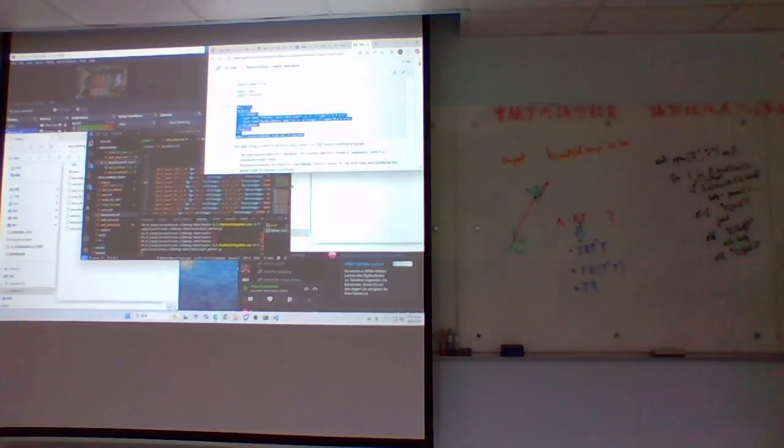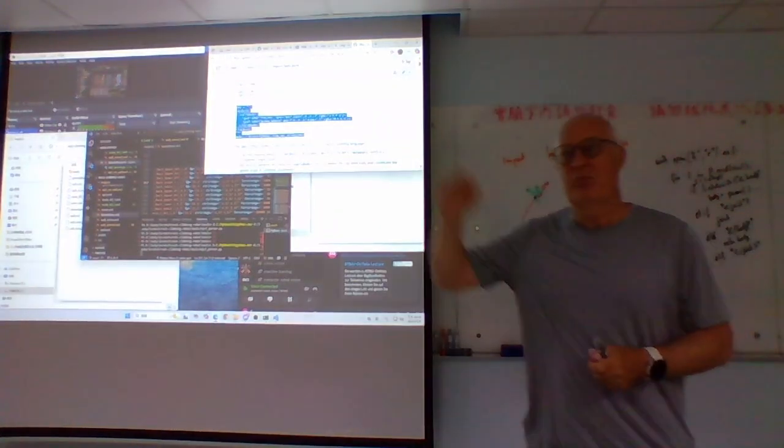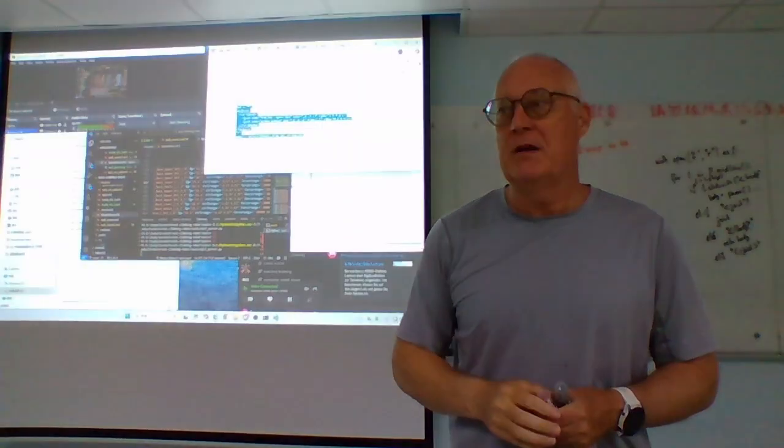So this would be a right hole. This is for the right hand. In this case, you want to go off on the tangent to some point here, bring the arm there first, and then pull it in. Instead of trying to go right onto that edge with zero millimeter error, I think it's better to assume that you have error, move it further off, and then pull the arm in.